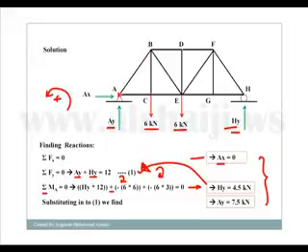That's perfect. Plus, it's very helpful if the joint I choose has an external force with a known magnitude, let's say AX or AY. In this case, AX is of course 0, and AY is 7.5.